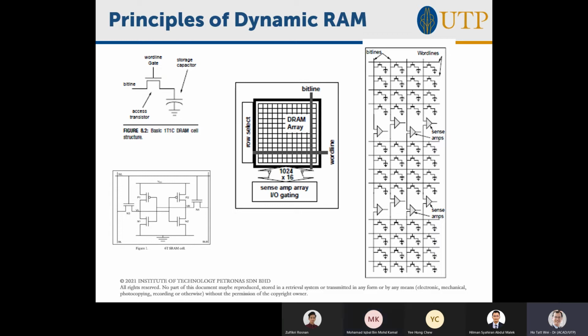Good. Follow your intuition. You're right, it doesn't retain voltage for long. It leaks, right? You know this from all capacitors. If you leave this for a while, after a while, you'll go to 0 volts. And that's the problem with dynamic RAM: once you charge it, it's leaky. You can't leave it for long. You have to constantly refresh, which means you check what the voltage is here and then you top up, top up, top up.